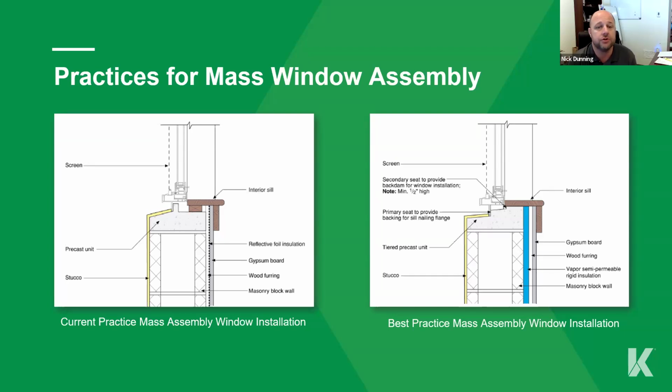And when we're repairing them, we're doing it properly with experienced third-party consultants and contractors because it is not stucco. It's a completely different system. It needs to be patched, repaired properly. And the foam systems that we see a ton, especially around '06 to '08, or '05 to '07 kind of boom, a lot of that is actually just stucco coated foam, which is a different detail altogether as well. I think we run into the thing the most is anytime someone sees something that's not stucco that looks like it, it's EIFS, when that's just not the case.